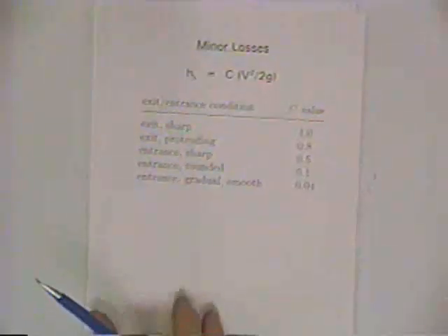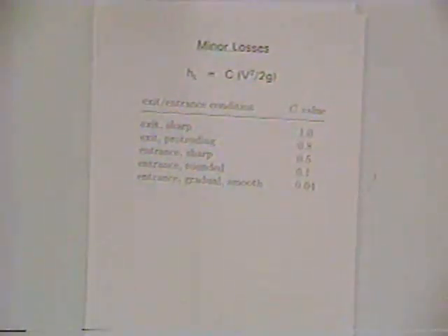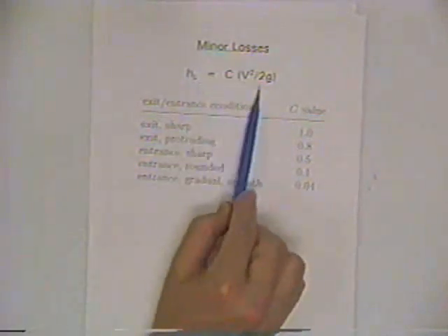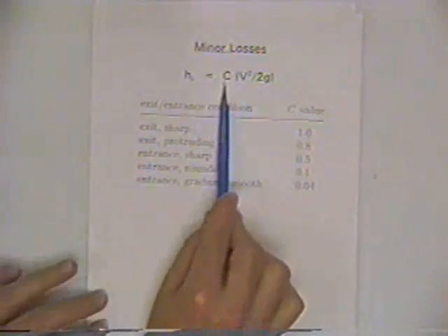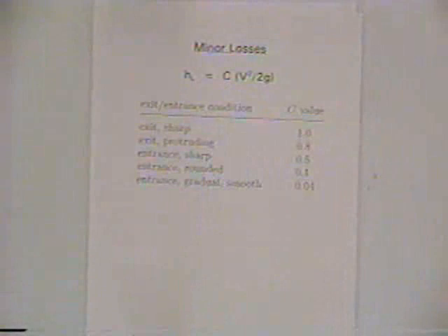And so a common term for these other head losses is minor losses. And in many applications, the minor losses might be quite major, but that's what we call them. They can be expressed in different formats. In your reference manual, the formats are always in the general form of head loss is some minor loss coefficient times a velocity head. And your reference manual uses the term C for the minor loss coefficient. In the literature, there are volumes that give minor loss coefficients for different types of valves, different types of fittings, and so forth.